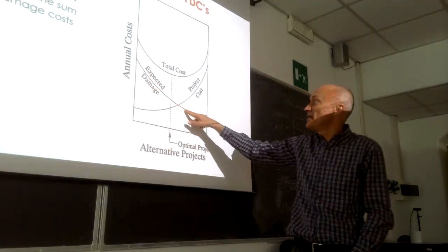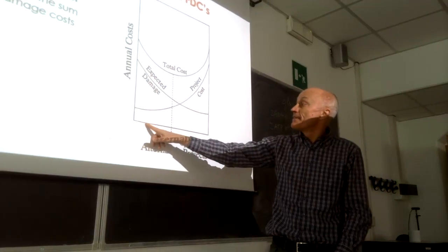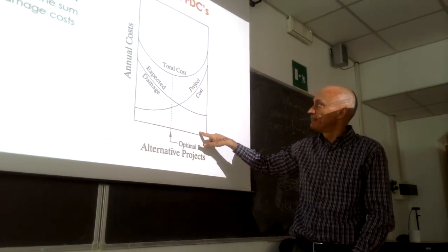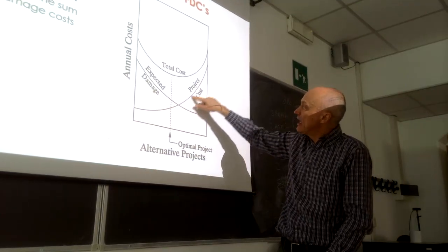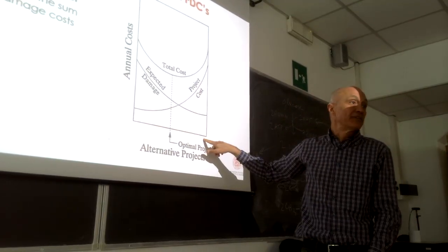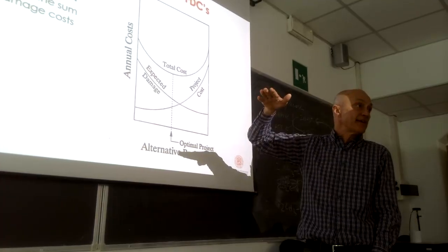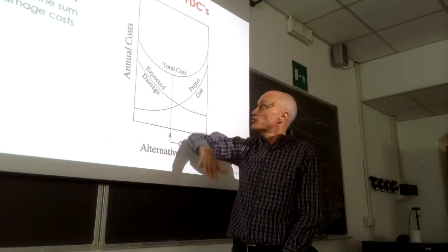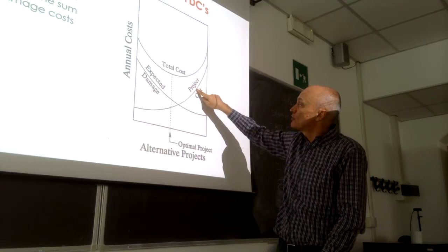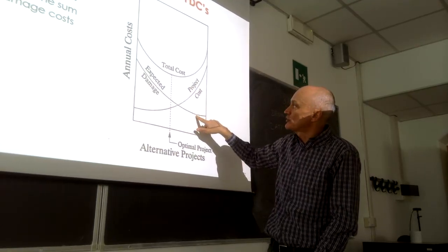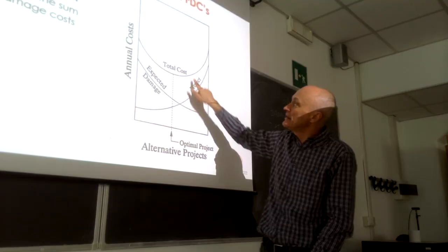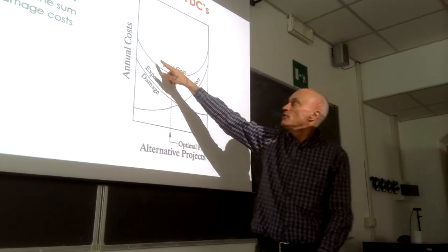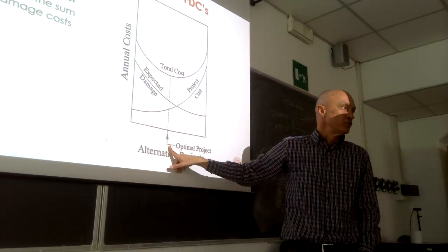You build a higher levee, you spend more money, right? So the stronger your defense system, the higher the cost and the less the loss. And what you are interested in is your total cost. So through a graphical comparison, you can identify the optimal levee height that minimizes the overall cost, consisting of the cost for the mitigation measure and the cost you incur because your orchard gets flooded.